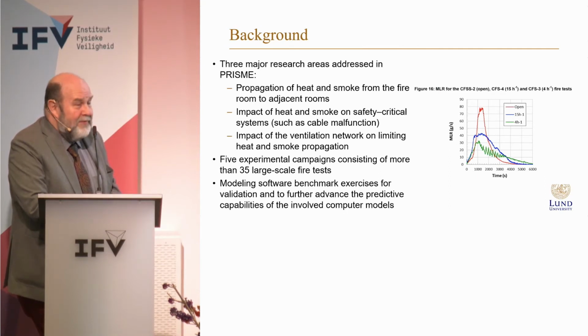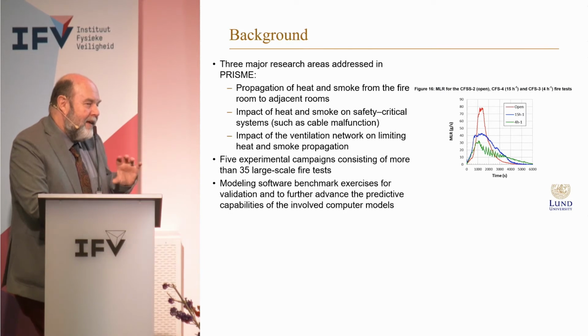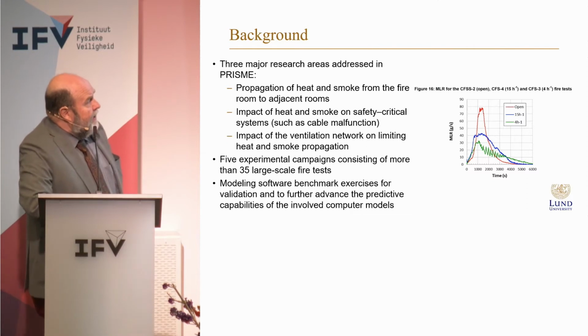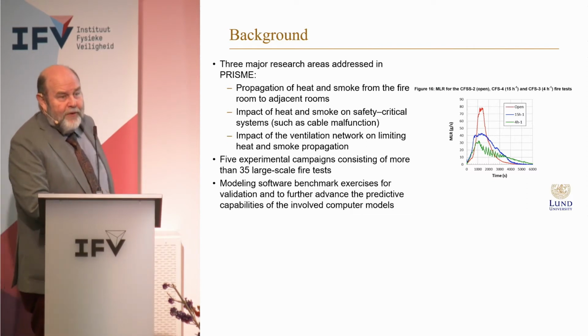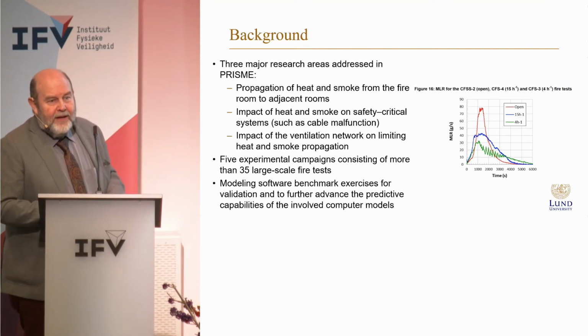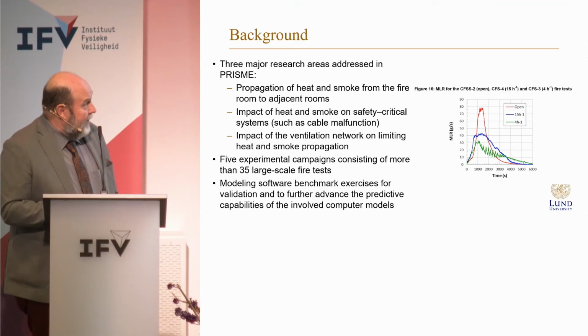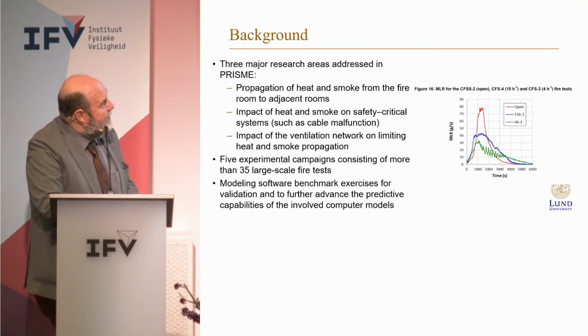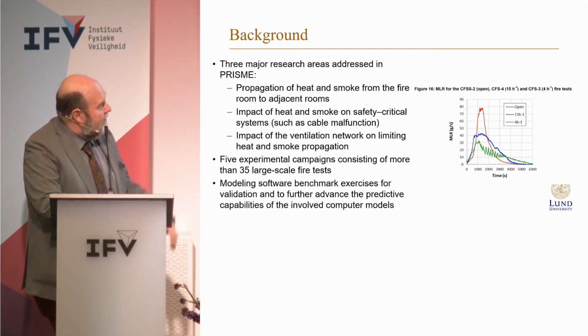An example here to explain how this mechanical ventilation can affect the fire. This is a mass loss rate, or you can also call it, if you combine it with the heat of combustion, heat release. The red line is an open configuration of cable trays. Let us say 3 cable trays start to burn and reach a mass loss rate of about 17 grams per second. So, if I remember well, it's then in the order of maybe 300 or 400 kilowatts.